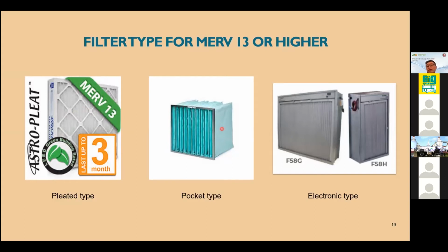So sometimes they even talk about HEPA filter. It is impossible for you to retrofit a HEPA filter because you have to do a lot of things. Let's say the building owner wants a HEPA filter, the best, higher efficiency filter, maybe rated at MERV 16 or 17, able to perform at 3 micron with a very high efficiency rating, 99.97% efficiency.